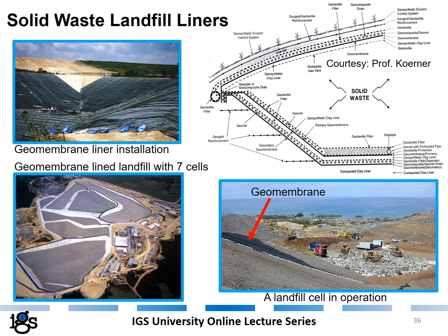Solid waste landfills are applications where geomembranes and geocells are used extensively. Here is a typical cross-section of a landfill with the base liner, and I will mention the closures a little bit later on.